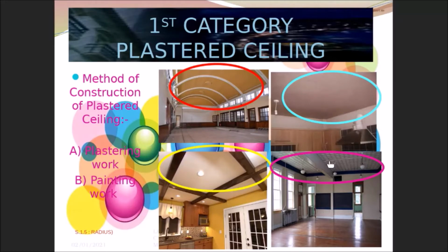So basically kind and quality, the shape and the type, if they are different, you cannot measure together. Even though all these four items are required to be plastered and painted, maybe the color has been identified by the architect, so you cannot measure similarly.